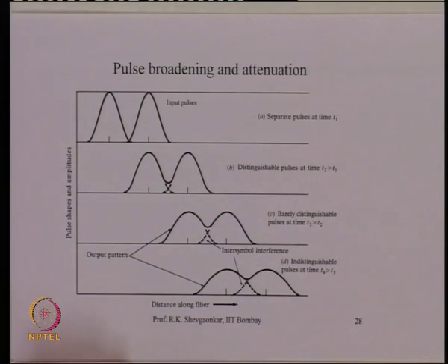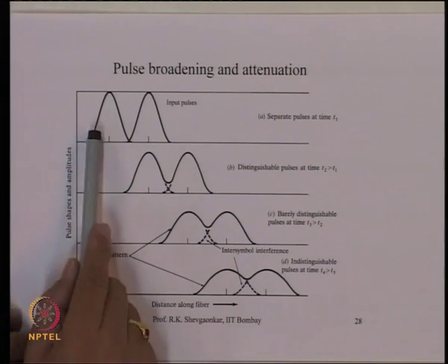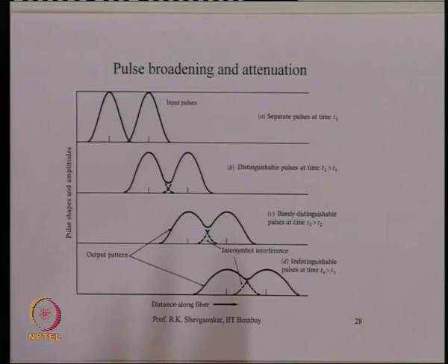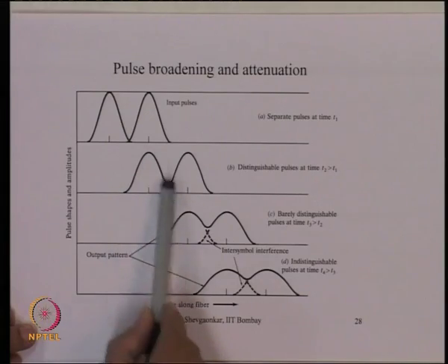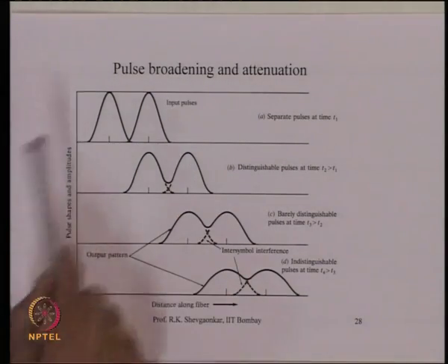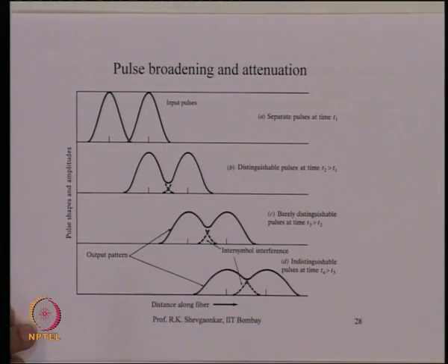So, if we send a signal in the form of pulses, what dispersion means is, as the signal travels on the optical fiber, the pulses get broadened. Here we are not even talking about the shape of the pulses, or whether the shape is retained. We are saying that if this pulse was representing the presence or absence of a bit, then as the signal travels, essentially this function broadens because of the phenomenon of dispersion, and as it travels more and more, the broadening becomes more and more.